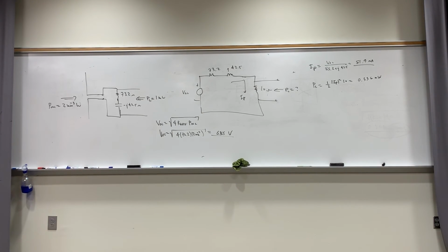So we just had one like that. Yeah, you've had a lot before. We've had about 5 or 6 problems with that. So definitely we'll have to know all of the max directivities for each case. Just 2 cases, short dipole and half-wave dipole. For the loop antenna, the directivity is 1.5. And the gain is the same, sine squared theta is the pattern.